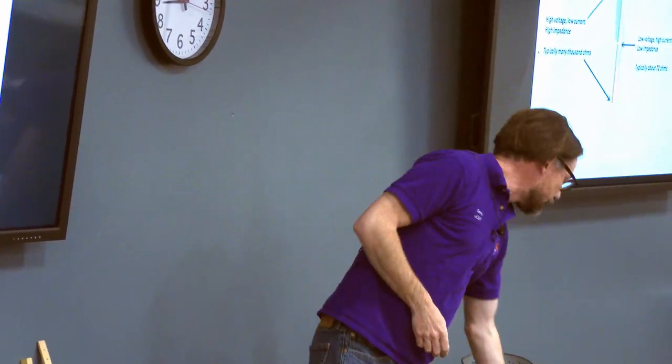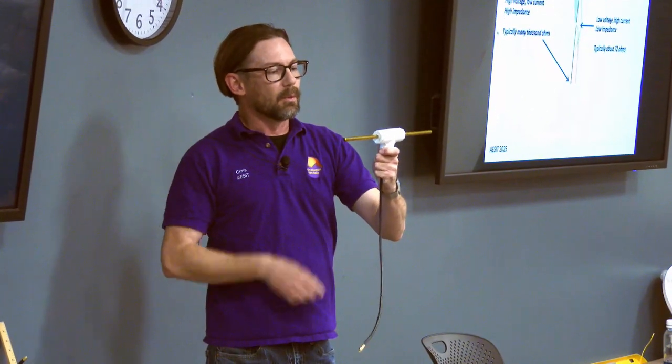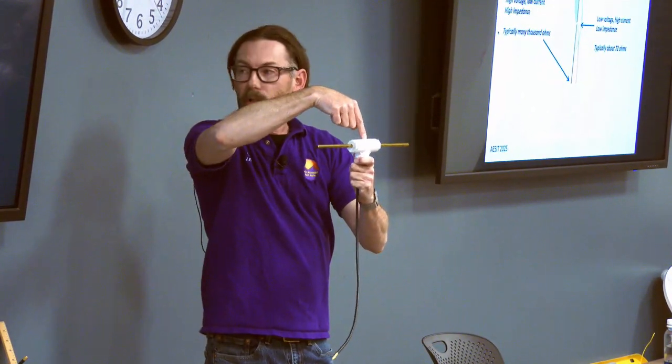In the middle of a dipole, like a resonant dipole, the ratio of voltage to current at that point is about 72. 72 what? 72 ohms. It's volts divided by amps. Gives you ohms. That ratio right here, 72.